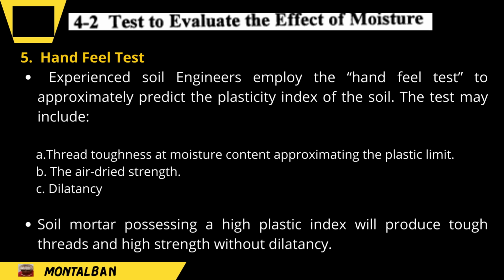Hand feel test. An experienced soil engineer employs the hand feel test to approximately predict the plasticity index of the soil. The test may include thread toughness at moisture content approximating the plastic limit, the air dried strength, and dilatancy. Soil mortar possessing a high plasticity index will produce tough threads and high strength without dilatancy.